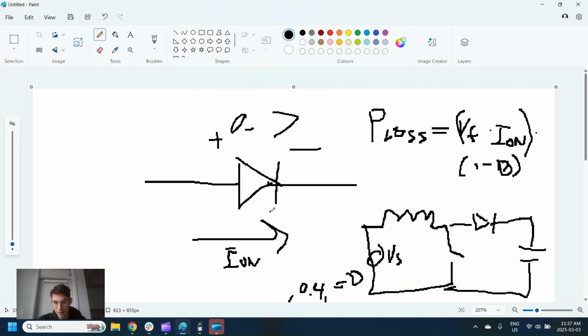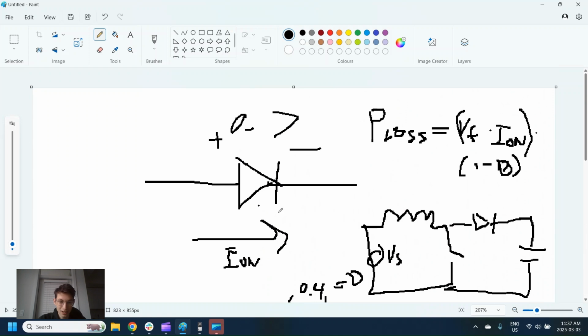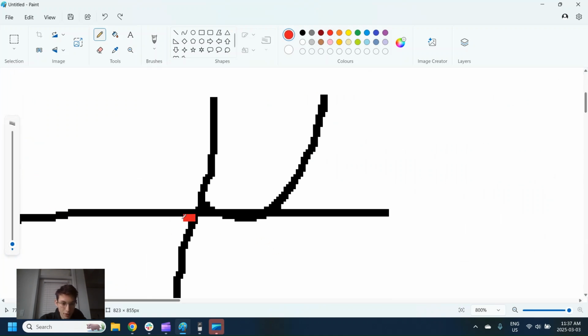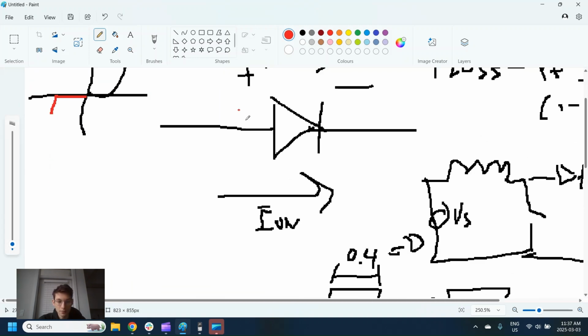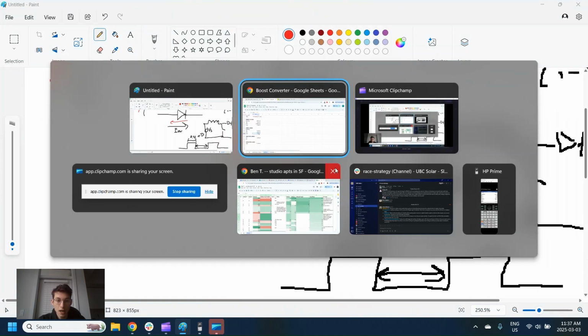This is basically just the fact that we want it to be an open circuit when we try and push current back through this way. But it's not going to be exactly that. Our classic diode curve is where we ramp up like this, and then here is 0. Well, in fact, there's actually a very, very small leakage current here before it drops off. So when we try and push current through here, there's going to be some that gets through.